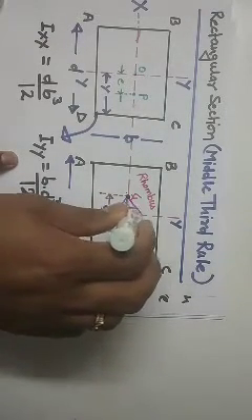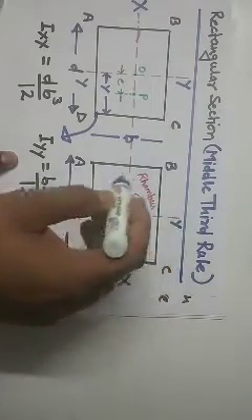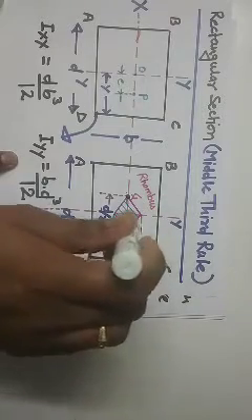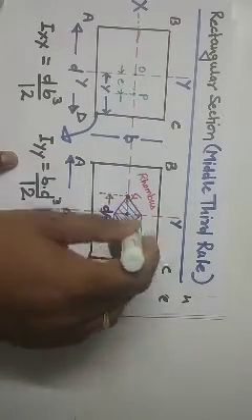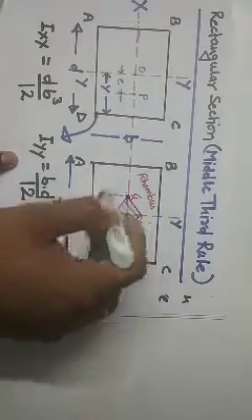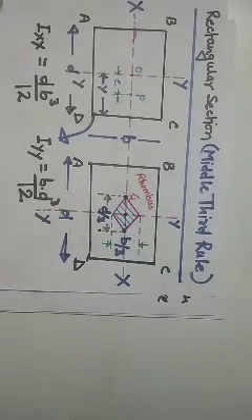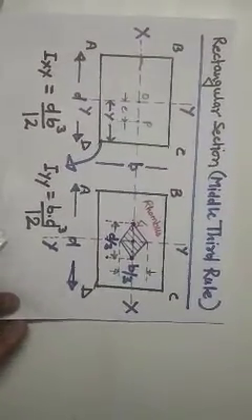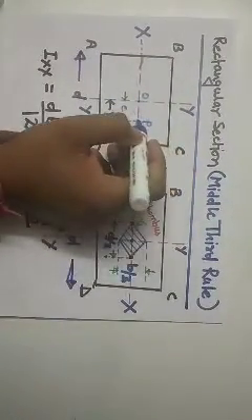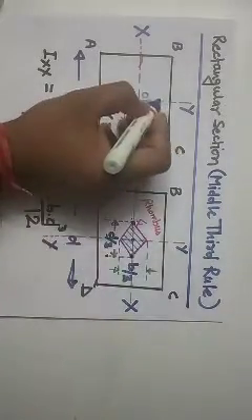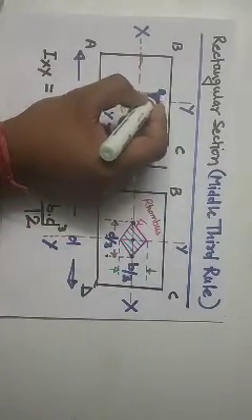If we put our compressive load beyond this barrier, there will be chances of tension in the section. When we put our direct load in between these points, then there will be no tension all over the face of this section. So this is the conclusion from this result. Now similarly, if the load is placed on the y-axis, here it is point P, and here it is point Q. Clear?